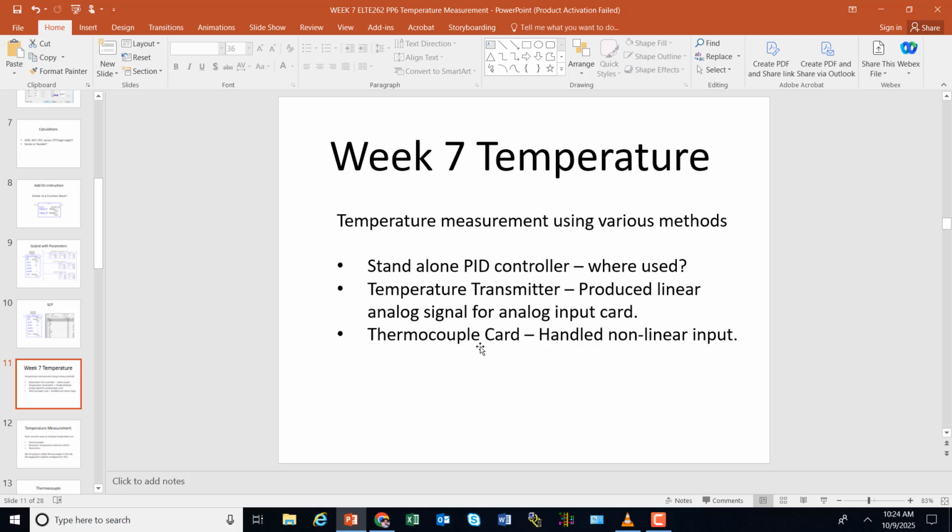Thermocouple card. That's another one that we're going to put a card in. I got a couple of these cards, so we're going to have to share equipment a little bit. The good news with the thermocouple card is we're just going to wire across PLCs. I only got a couple of them, so you can steal the I/O off of this, because we talked about in input you can use somebody else's as a remote rack and share input data.